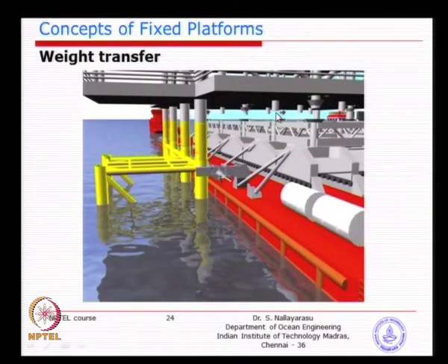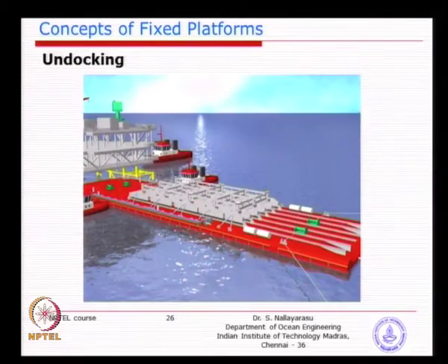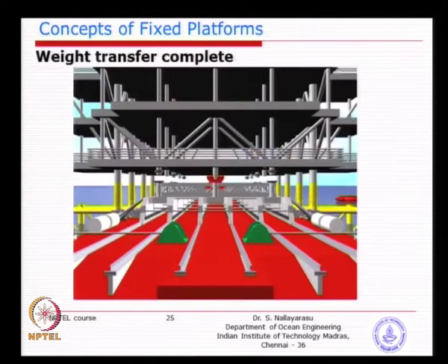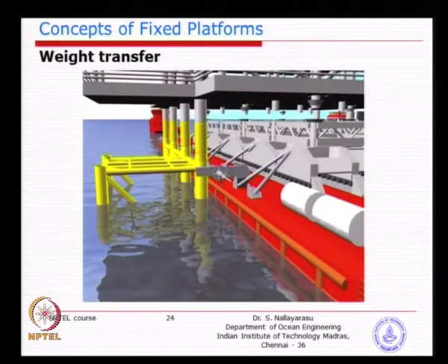Once you start welding, you can see here several fellows have gone there and disconnected the supports, and unless you disconnect the supports, this barge cannot come out, is it not? So, you go and disconnect the supports, quickly pull the barge, the way it came in you have to reversely pull out. What will happen otherwise? If you pull out in the same direction, the structure that you have installed will get damaged, because there will be a bridge, there will be a mast on the ship. So, basically you will have to go in the reverse direction, the way that you came in, and just go outwards.